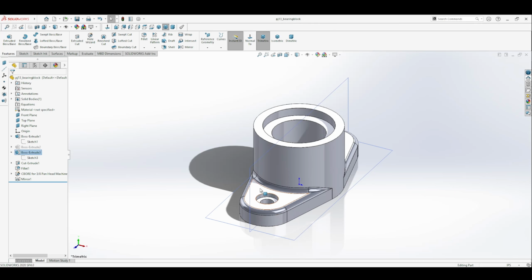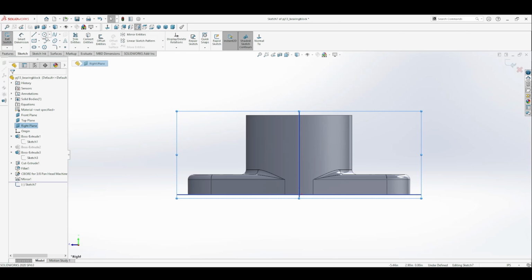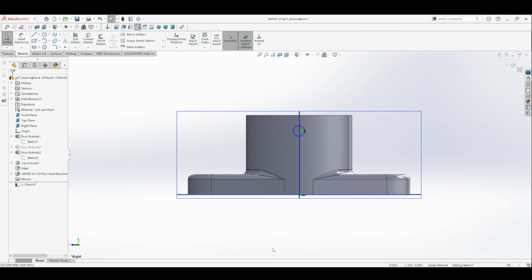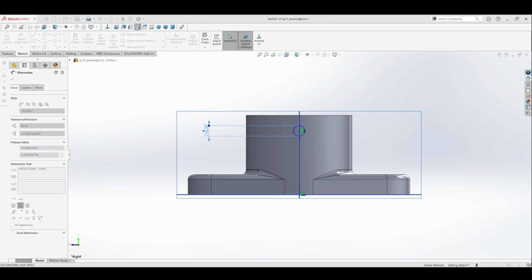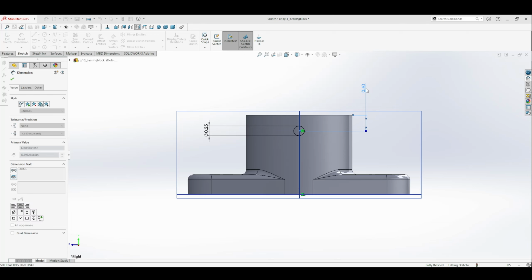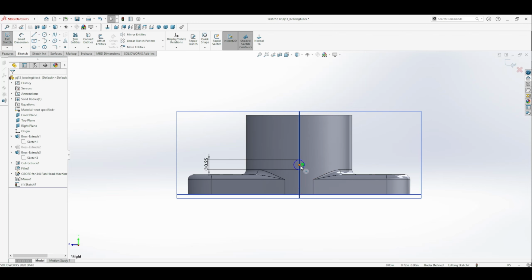So we'll take from the plane, normal to, it'll be an extruded cut, and it's just a circle. And the diameter is 0.25. And we'll take it from the top here. See what 1.25 shows us. No, it's not that. So let's get rid of that dimension and try again.